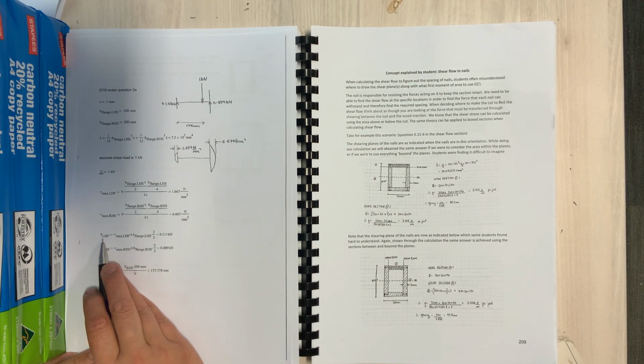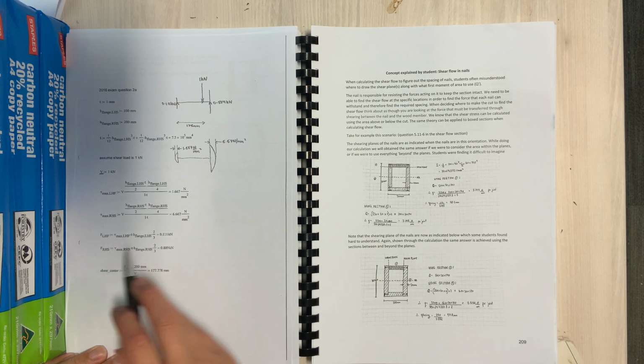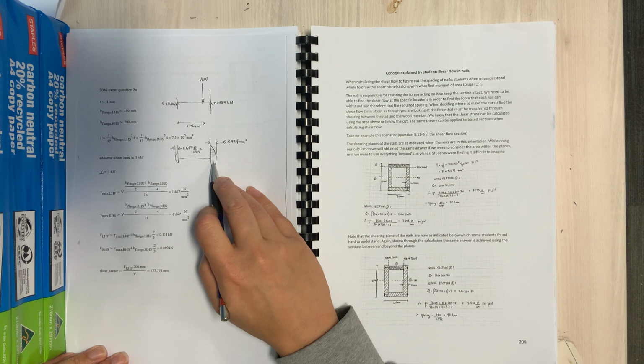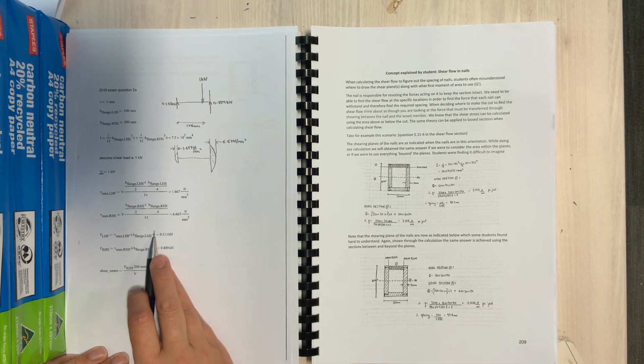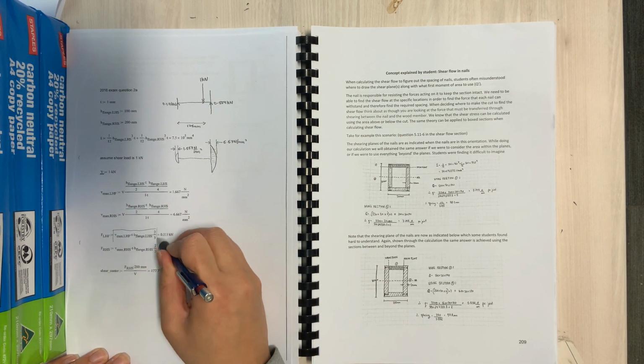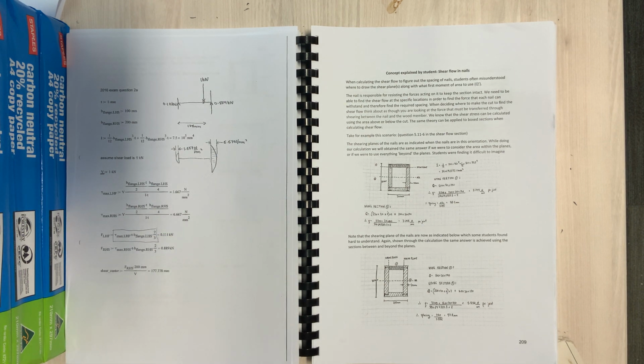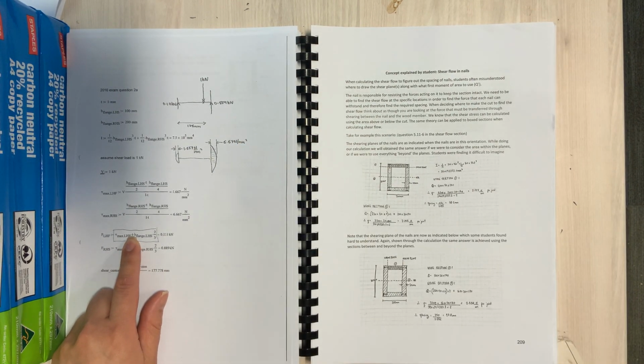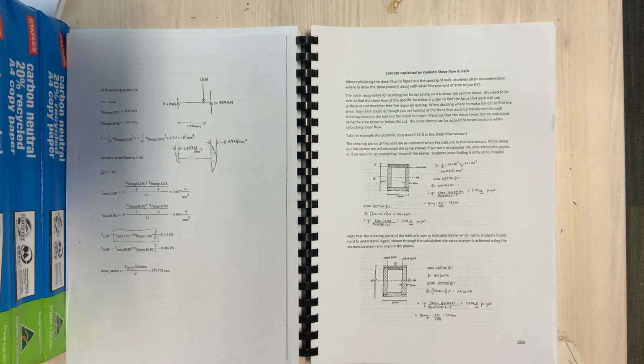And then you can take moments. Well, firstly, you can integrate under that area to work out the area under the parabola. There's a rule which you may already know, that the area under a parabola is 2/3 of the stress times the total length, and times T times B. If you don't know that rule, which you may have covered in geotechnics by now, you would definitely know it after we've done the virtual work section. So don't worry, but that's how we can get the area under a parabola.